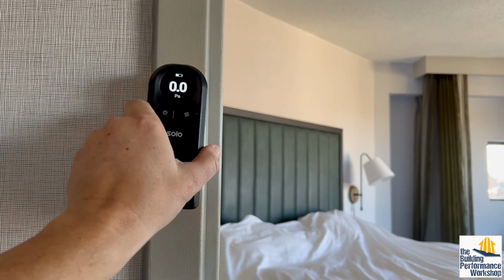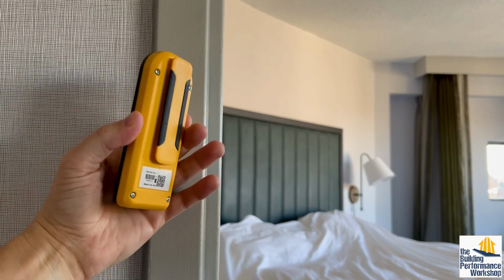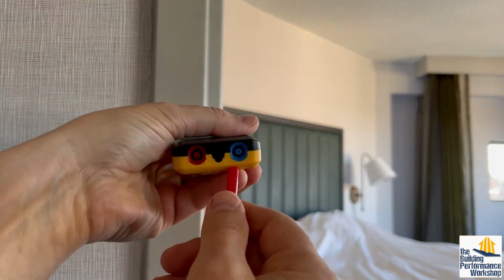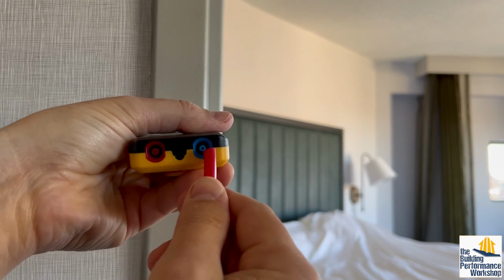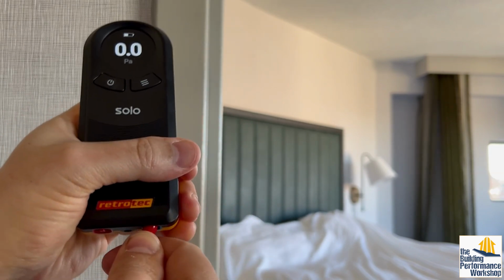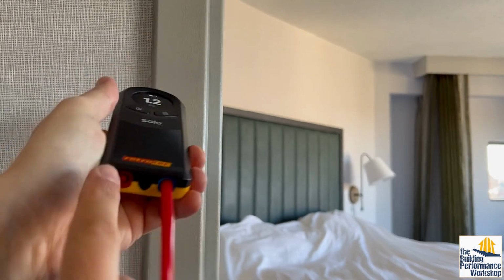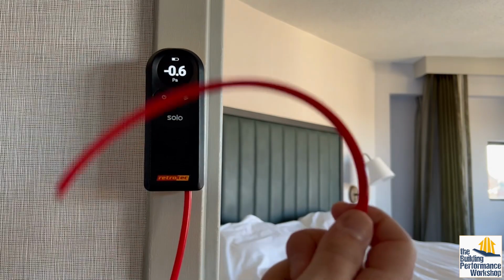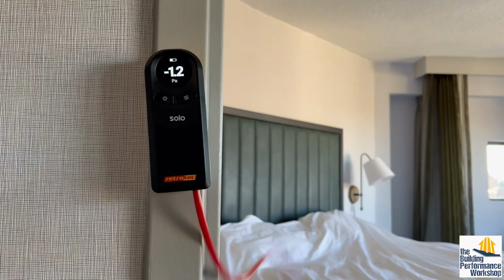So this is your 1-channel manometer. Again, this is $400. Got magnets on the back, which is why it's floating here. We've got 2 ports down here. We've got positive and negative. We can call this input and reference. If we want to know what the pressure in that room is with reference to out here, when we hose it up like that, and then we take the end of our pressure hose, throw it in the room, and then we close the door, so that the hose is in the room and we are out here.